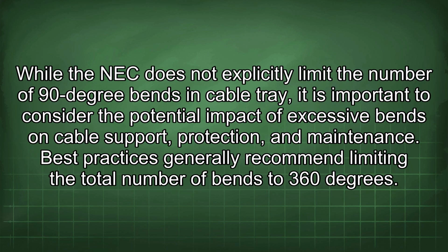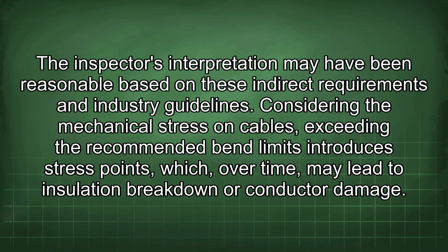While the NEC does not explicitly limit the number of 90-degree bends in cable tray, it is important to consider the potential impact of excessive bends on cable support, protection, and maintenance. Best practices generally recommend limiting the total number of bends to 360 degrees. The inspector's interpretation may have been reasonable based on these indirect requirements and industry guidelines.